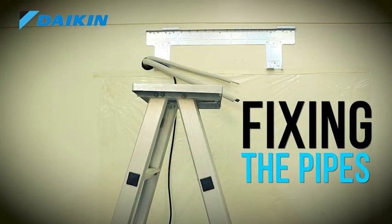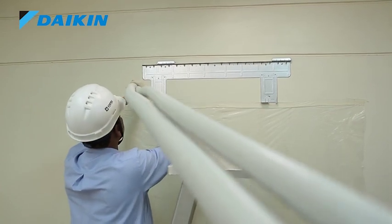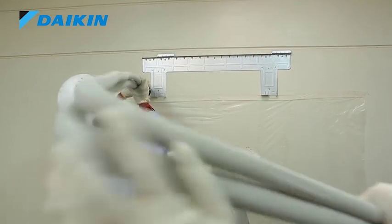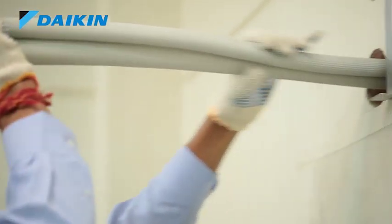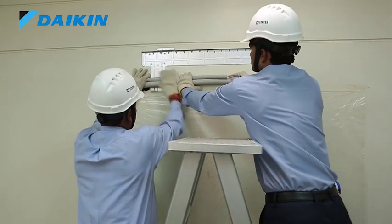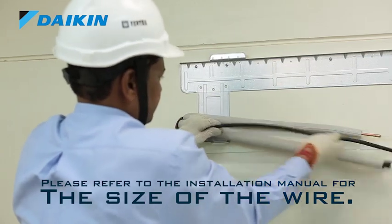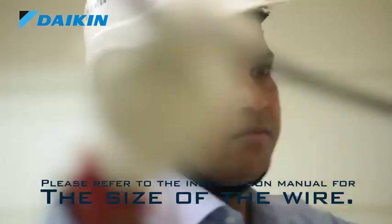Fixing the pipes. Now, as the next step, take out the copper pipes that were covered with insulation sleeve and the electrical connection cable from the hole that was drilled in the wall next to the indoor unit. The size of the wire must be as per the specification mentioned in the installation manual.